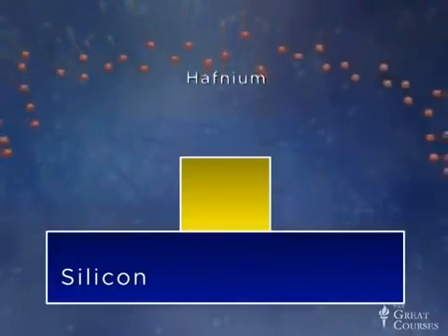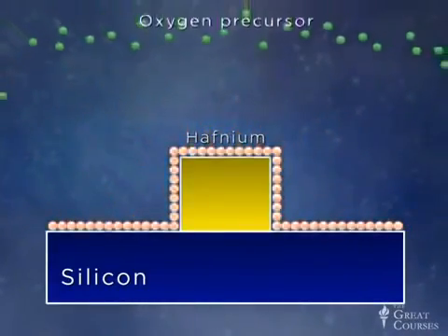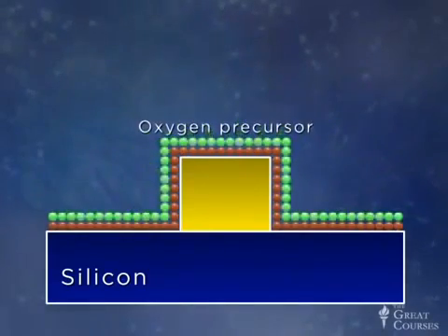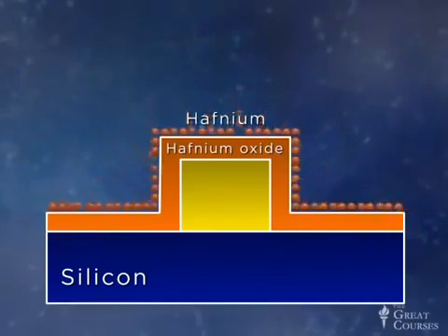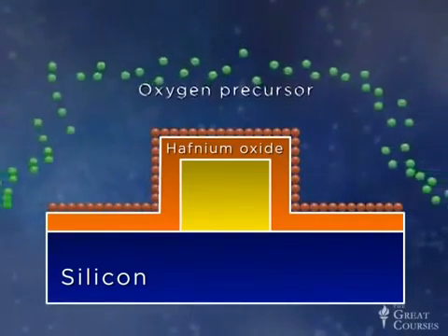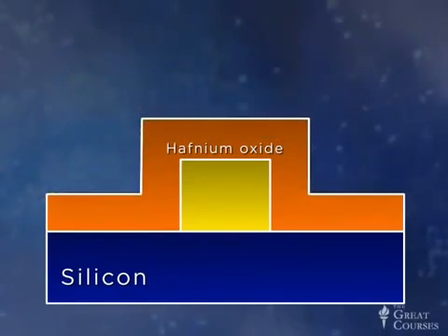Now here, ALD, atomic layer deposition, is very much our friend, because we're going to try to wrap things. We can't just have a process of depositing an oxide that's directional, that will only grow vertically. We need a wrapper. We need a nanoscale wrapper. And atomic layer deposition provides a technique where, because we're working with the chemical reactivity of surfaces, because the hafnium atoms will stick to the sides as well as the top, we have a technique that's very prone to creating a nice, compact, continuous, consistent wrapper all the way around the edges of one of these transistors.